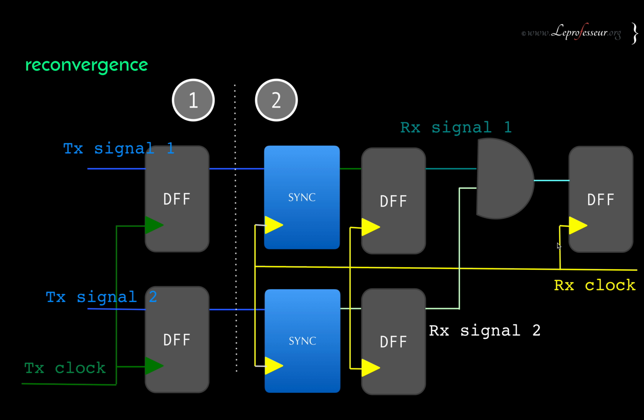So think about if the RX clock and this signal is toggling too much, it's a dangerous thing here, because this flip-flop may go into metastable state sooner or later. So you may have to put one more synchronizer here in order to properly use this signal. One more synchronizer after the AND gate, or do something else.